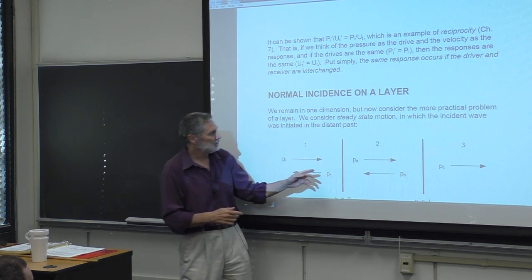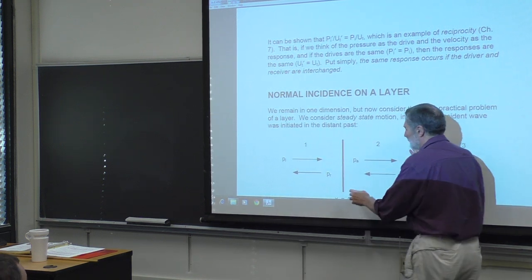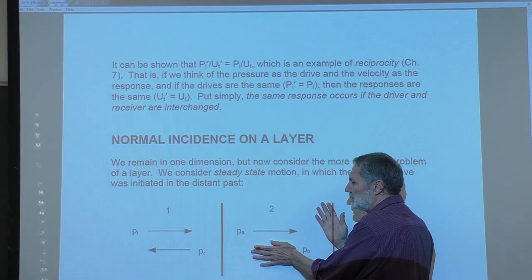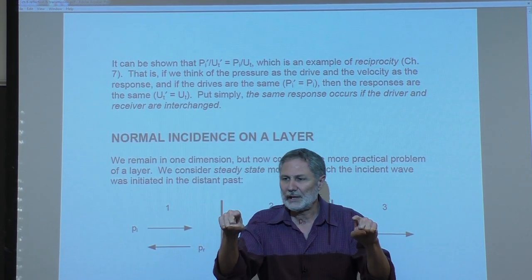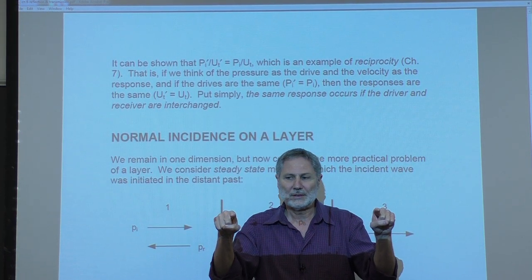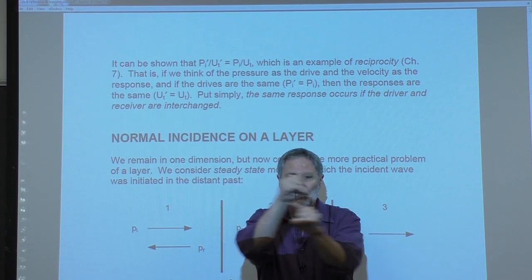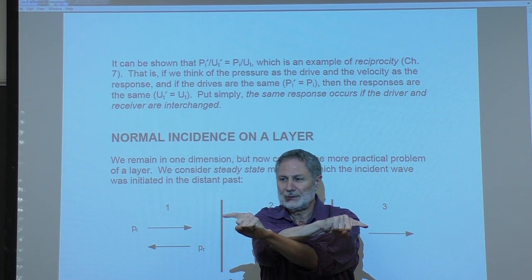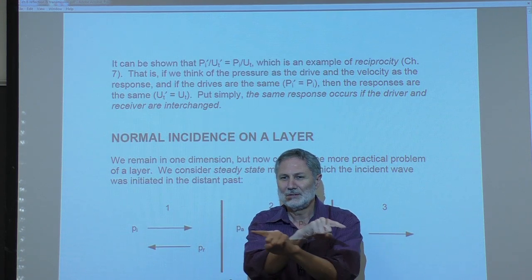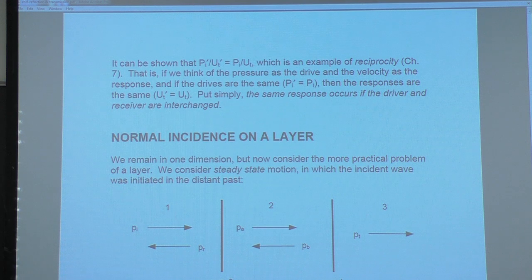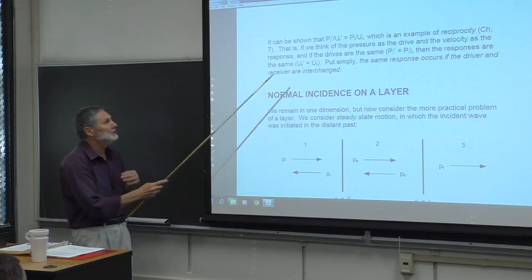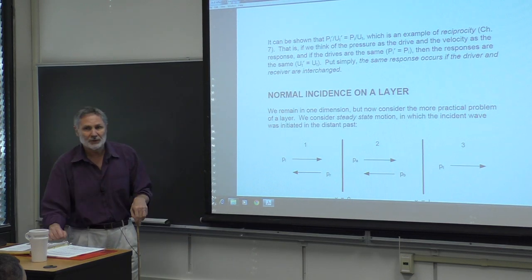We did it in this case, but you could have a continuously changing medium. You have a drive point and you're picking up the response at another point. If you switch the two, you get the same response, no matter what's in between, no matter what it's doing. It's remarkable and not obvious at all. That's called reciprocity. So we're going to go into this in much more depth in the next chapter.